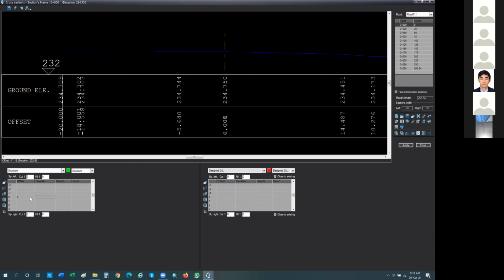And elevation is, you are working with something called elevation. It's the type of installation that is on your machine. You see it says elevation? Yes. But it's supposed to be DH. Everybody, please pay attention because it's a very common issue where people have problems and something goes wrong. The system has two ways to work. One, we call it elevation, and the other one, we call it DH. Elevation is where you work with absolute elevations. It's when you don't have a profile. But since we designed the profile, we have to change it to DH.